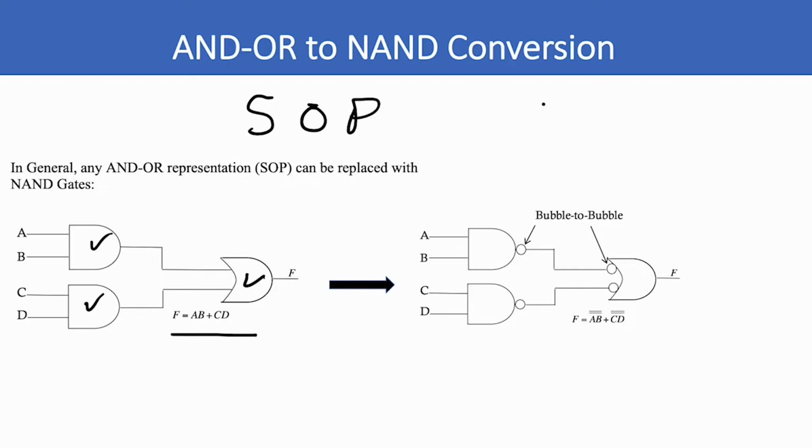And the reason is, electrically, to implement an AND gate, you're going to get a natural NAND gate from the electrical circuits, and then you'll have to create another inverter to get it back to AND again. So to create an AND gate, you have to add another stage of inversion. So it takes more transistors, more gates, more power. So the natural gate implementation from a circuit implementation standpoint is the NAND gate. So that's why most of the time you use NAND gates for circuit implementations.